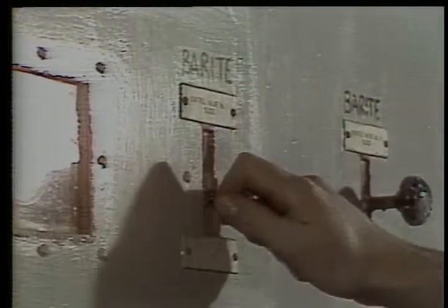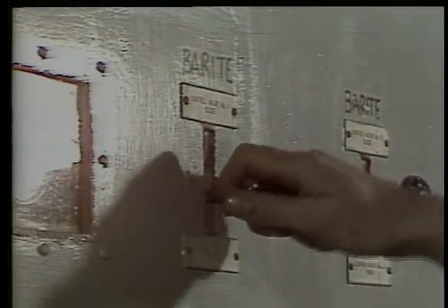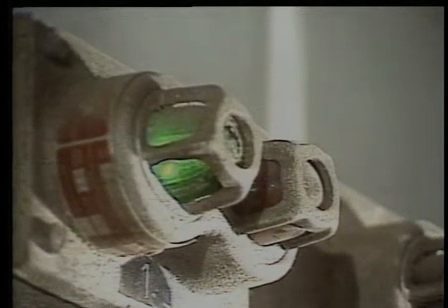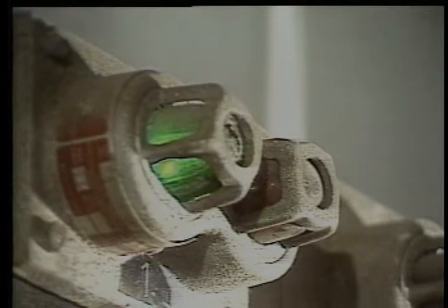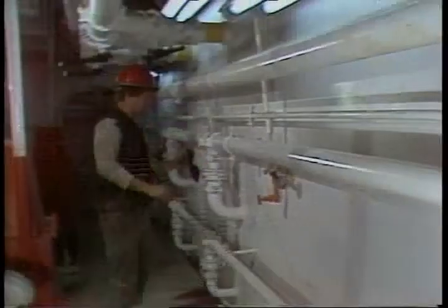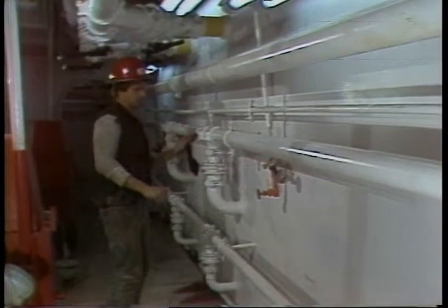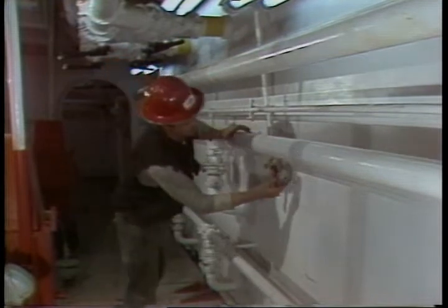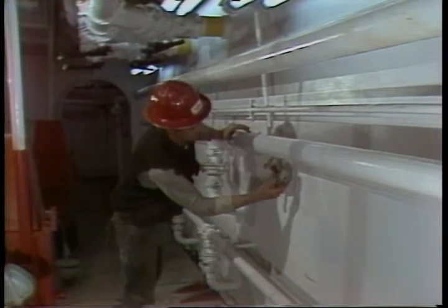Next, the vent valve is opened at the destination tank. On this rig, this valve is operated remotely from a panel, since the vent valve is on another level. Then, all of the pass-through valves from the source tank to the destination tank are opened, except for the valve at the bottom of the source tank. The purge line is turned on to get an airflow established.